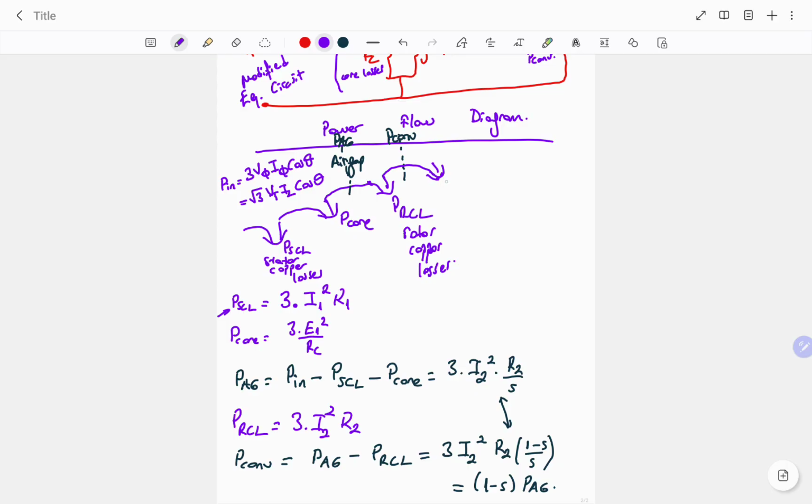So because of this, here we have the mechanical losses. These are friction and windage losses. And the next one will be the stray losses, which are generally defined as the undetermined losses of the system during construction because of the tolerances of the materials or the conductors.